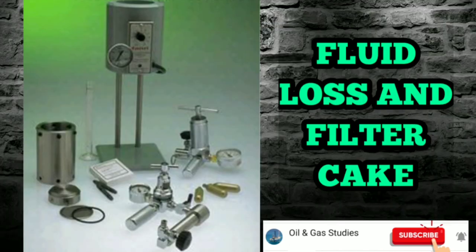Sixth is fluid loss and filter cake. Fluid loss. Unit: milliliter per 30 minutes at 100 psi for API test, or 500 psi and BHTF for high temperature high pressure, HTHP. Filter cake thickness: 1/32 inch.